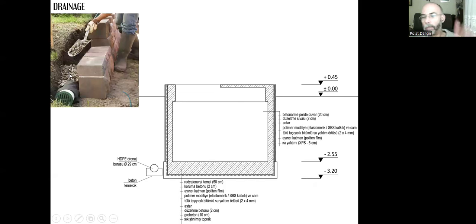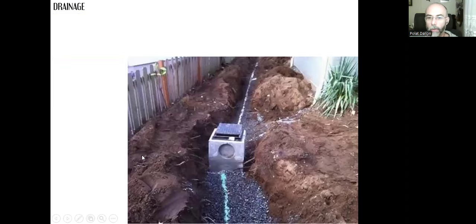And we mostly place gravel and sand as the layers above the pipe so that the water will be filtered. We don't want our pipe to clog. And this white line will represent the direction of the pipe.